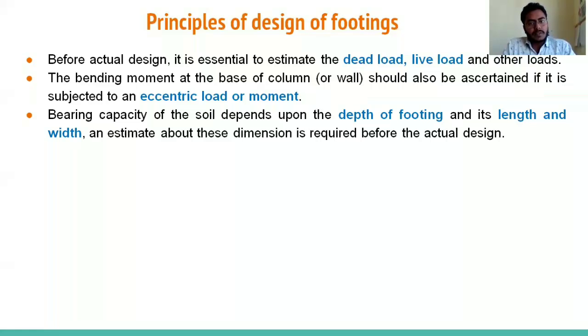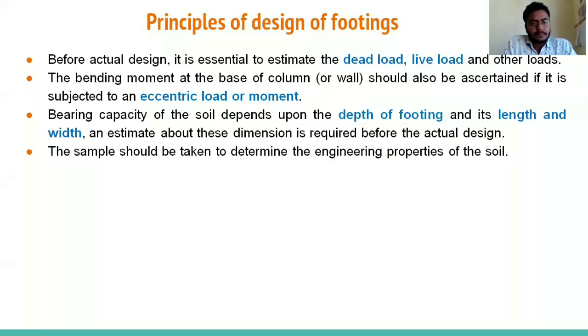The bearing capacity of soil can vary, and you can select the depth and length of the foundation according to the bearing capacity of the soil. So we have to be very sure about that. Samples should be taken to determine the engineering properties of soil, like bearing capacity. Also, many other tests we have to do to know the engineering properties of soil for a better design.